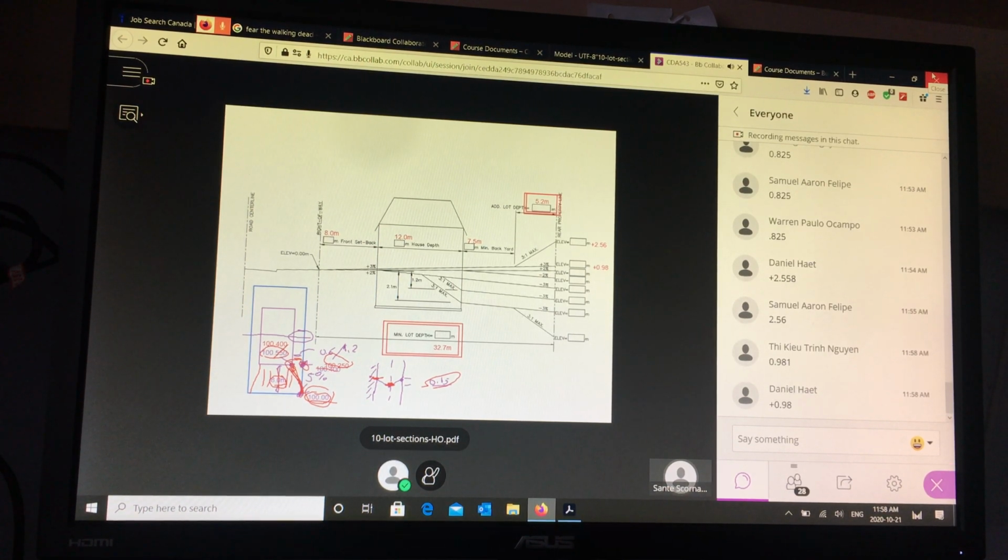Okay. So if the backyard was about a meter higher than the front, you'd have a front draining lot where the entire backyard is usable. It's 3%, maximum 5% internally. And that's great. That'd be good if I could use the entire backyard. But again, it depends on where the existing ground is.